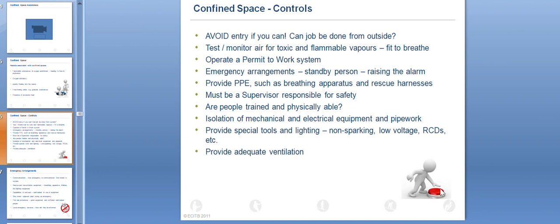As we saw in the video, for all diesel tanks and all confined spaces, we make sure we have a work permit. After the work permit, we make sure a confined space watcher, a standby person, is there, monitoring the login sheet, like attendance. If someone is going inside, they must sign their name and time, and once they come back from the confined space, they should again sign the out time. Then we can control their attendance.